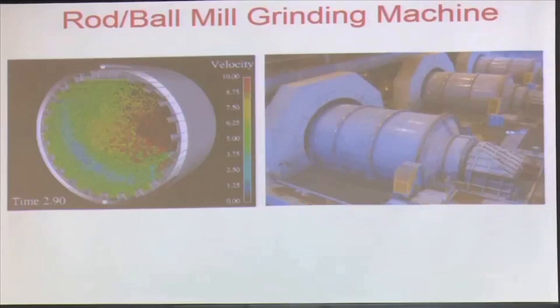Because of rotation, what will happen? When it is being lifted, there will be abrasion between the surface of the machine and the particles. There could be abrasion between particle and particle, and between the steel balls and the materials. So, many types of abrasion are there. Abrasion generates much finer material, and then when it is lifted, we allow them to fall freely. That is a calculation, what should be the RPM of this.